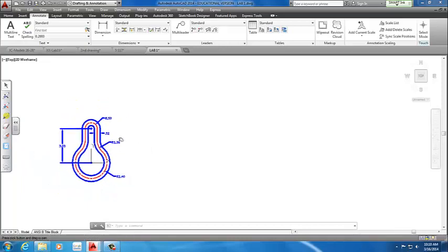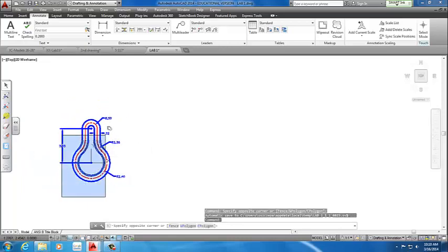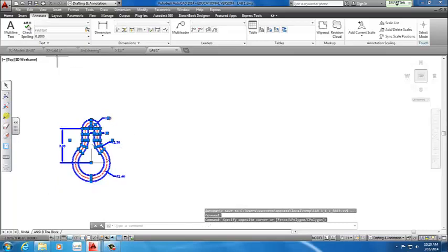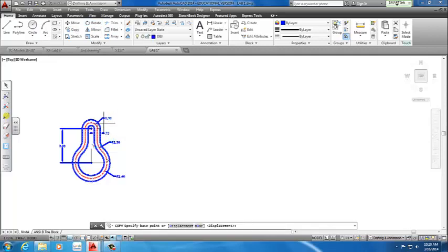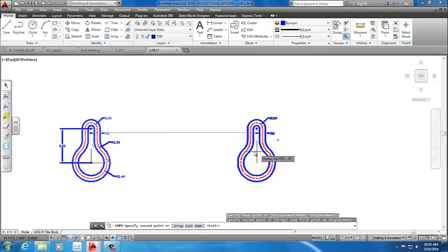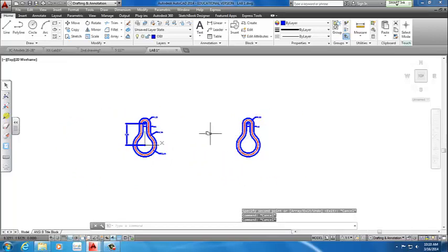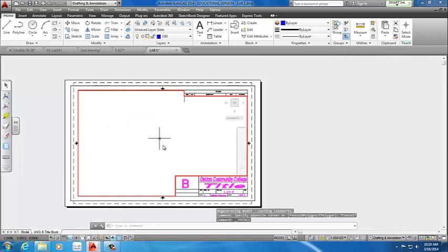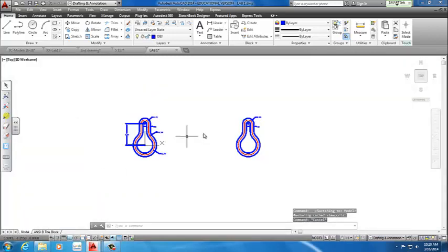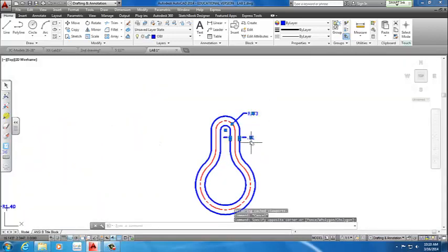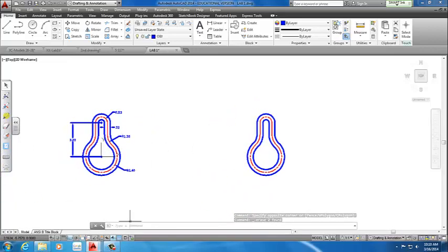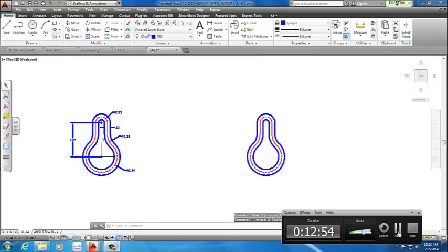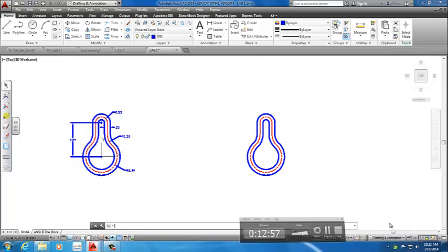To create the 3D object, we will make a copy of this entire object, including the dimensions if you have to. So we go to your Home tab, we go to Copy. We copy from any location, just about there. It doesn't have to be too far, as long as it doesn't show up in the viewport, which we'll get into later. Then you delete the dimensions because you no longer need those, and you have two drawings, one with dimensions, one without. Once everybody's caught up to this, we will make this a 3D object.